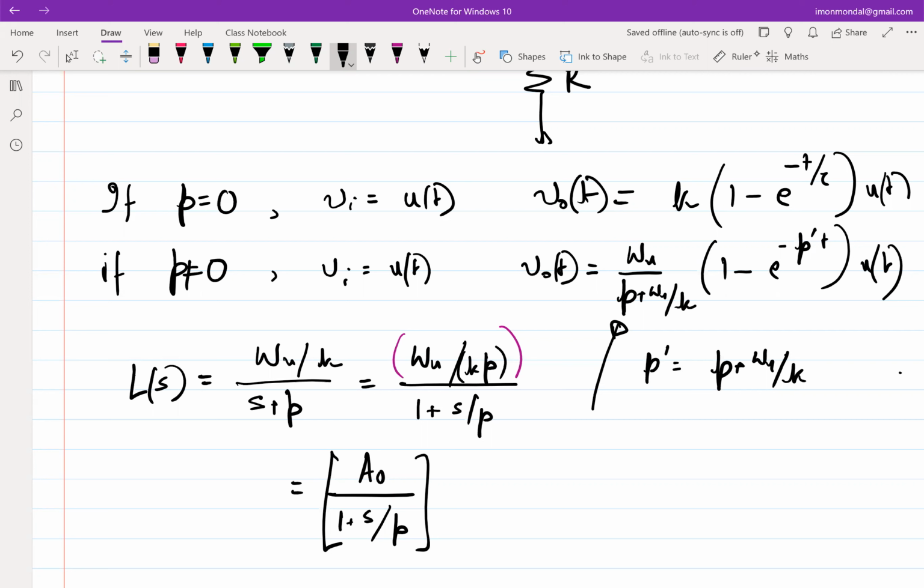So now one interesting thing to observe here is that, by the way, these limits are important because one might tend to think that if omega naught is 0 and I'm using the second equation, I'm getting infinite V naught. That's not true because the second equation is valid well beyond omega u over k, where the loop gain itself is much lower, which means that you're operating at omega naught much greater than omega u over k, and definitely more than omega u.